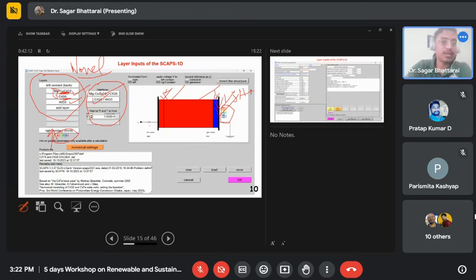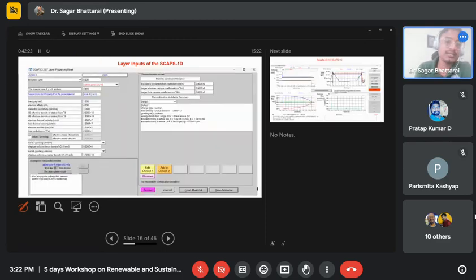All right. So as I told you, you have just designed this and it's not like that. If you click on the CIGS, I have just named it. So if you click on the CIGS, what will come? That CIGS here has a thickness of 0.5 micrometer. Remember that, okay? 0.5 micrometer means it's 500 nanometer. Okay, so CIGS material. Now you can have these inputs.